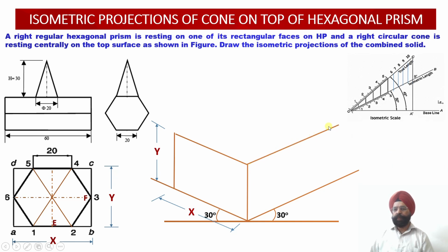The length of this prism is given to us as 60 millimeters. Now we'll measure 60 millimeters along the z-axis and then draw this vertical line over here, and again you can see it is an isometric dimension, and this is parallel to the y-axis, right?